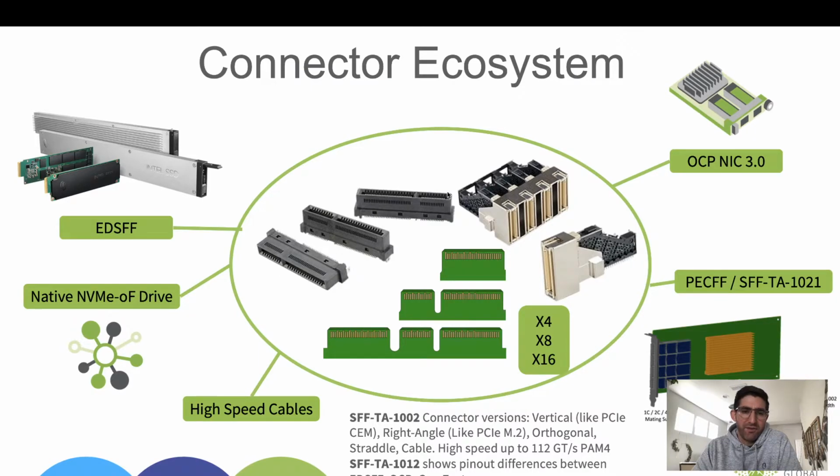And then you have, obviously, the different variants of the connector that you can use on a backplane or down on a motherboard as well. So the EDSFF family of drives are all going to use that, and we expect millions of units to be shipped on the EDSFF SSDs. So it'll be a pretty broad use of this ecosystem. But the OCP NIC actually uses the same x16 connector, this SFF-TA-1002. So that's really good synergy with the other stuff going on in OCP.